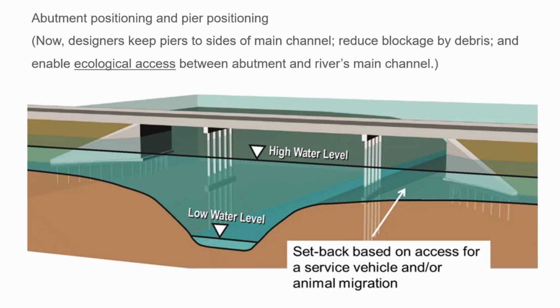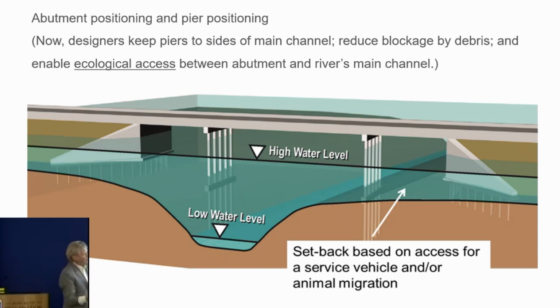You have a passage up here, which allows these days deer and other creatures to wander through, and so the span is a little bit increased. But typically, we keep the first piers quite close to the abutment, as you see here, in order for less blockage for flow, debris hang up and so forth through there. And I have illustrations of that too.